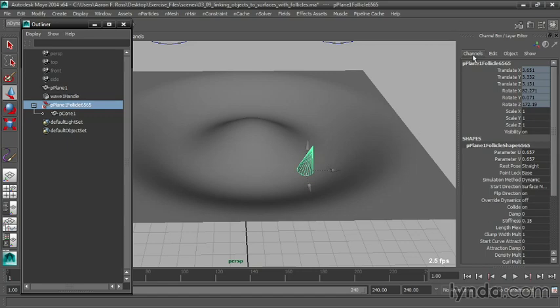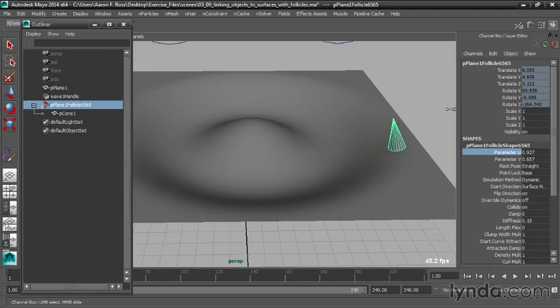But it's best if we go up to the channel box slider options here. I'll click the manipulator button a couple of times until these other icons light up. Remember, this is the speed of the channel box slider. We want it to be very slow, so we'll click that a couple of times until we're in slow mode. And we also want hyperbolic on, which means we'll just have better control. So I'll click on that arrow, make it a curved arrow, which means we have hyperbolic channel box sliders. And then just select parameter U, the name, and middle mouse drag in the viewport.